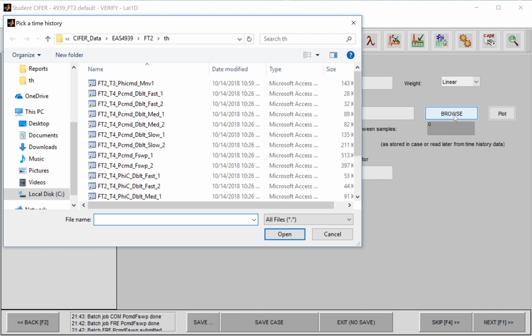What that is like, let's say you're using the frequency sweeps to do the system identification. And now you want to see how good is my model ID. Well, you don't go ahead and select the same sweeps. You can, but you really want to expose the model to a different set of data, one that it hasn't seen previously, because that's sort of the ultimate check. Now with brand new data, how well does the model perform?